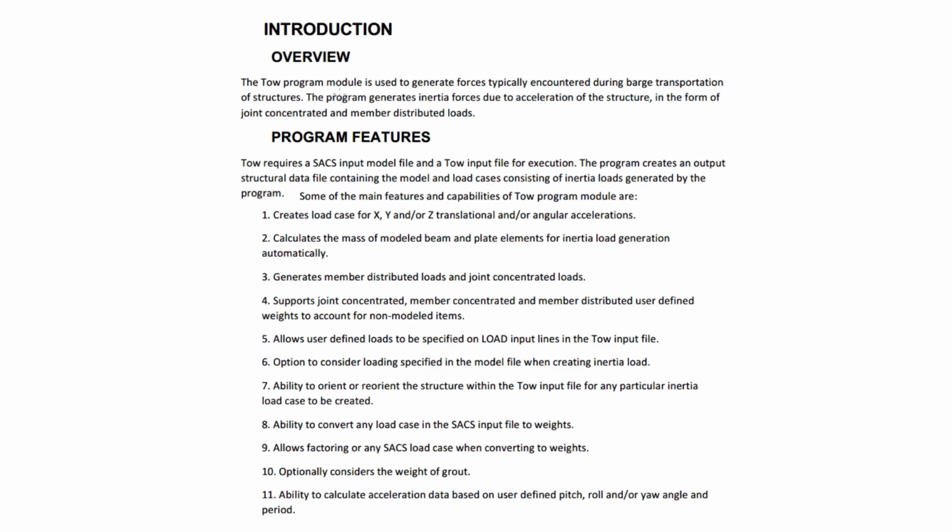Here we will see about the TOP program module capability and introduction. That's the one used to generate the inertia forces when we are doing the transportation analysis of any cargo. The TOP program module is used to generate forces typically encountered during the barge transportation of structures. When we are transporting structures using barge transportation, the structure will encounter inertia forces. Those forces will be generated using this TOP program module.